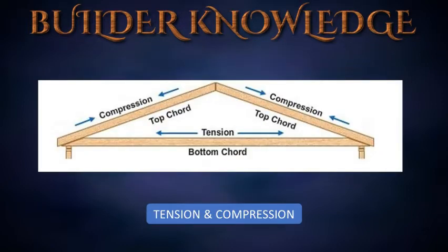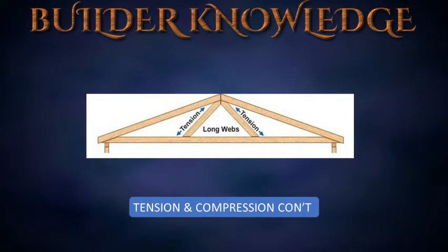Now let's cover roof truss construction procedures. The truss design deals with tension and compression. The top chords have a compression force, while the bottom chord has a pulling apart or tension force. The long webs support the bottom chord, placing a tension force on the long webs.